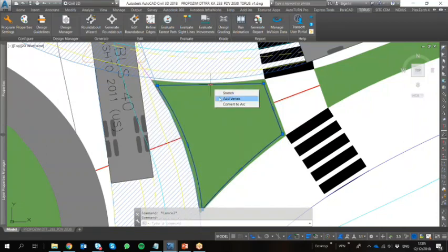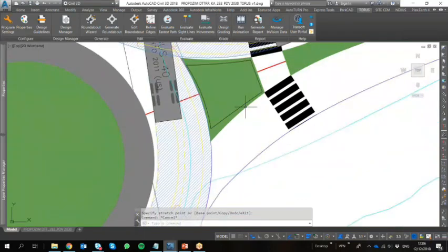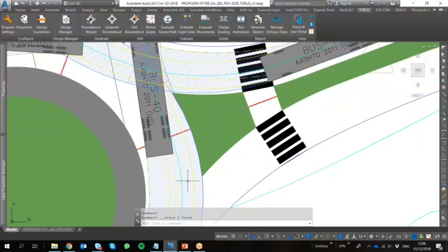So basically this is just to represent that we do not calculate the island as itself, because the island sometimes could be like this, or especially at exit maneuvers, in order to account for larger vehicles with a bigger nose, maybe like this. This is the island envelope. The envelope is the area where your vehicles, your design vehicles, do not go through.